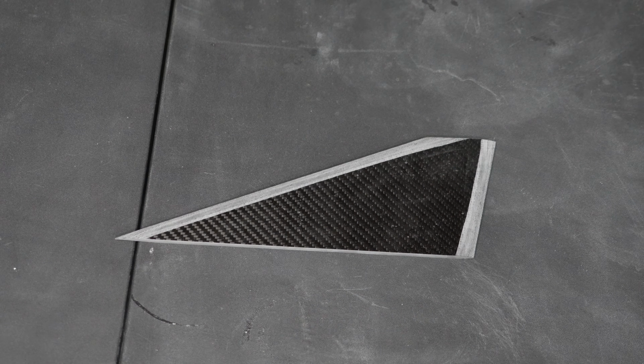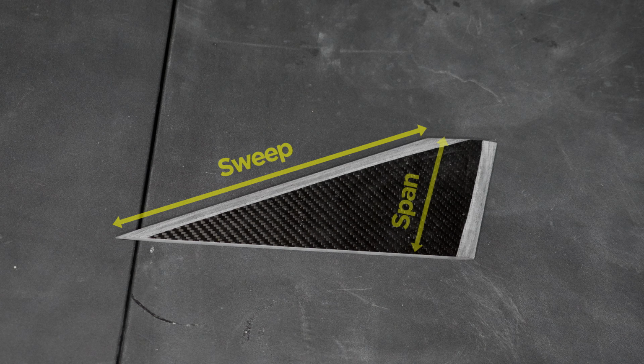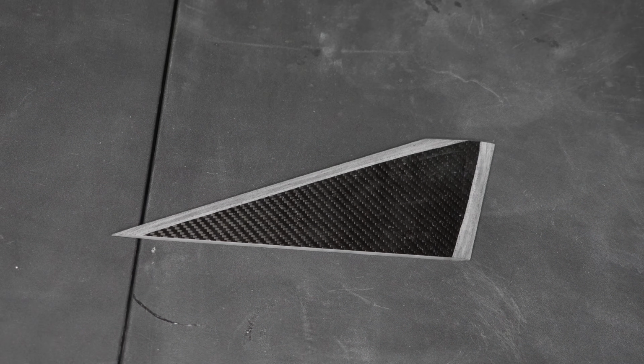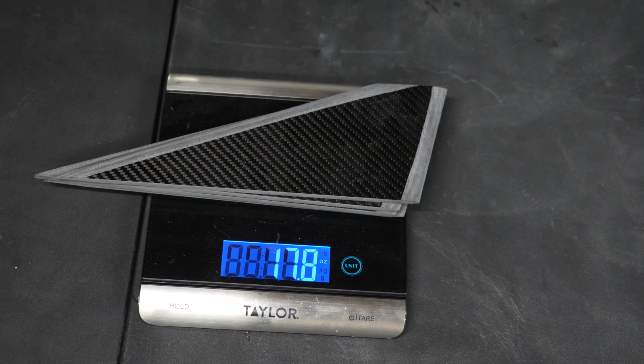Now we're on to the fins. You're going to want to measure the fin's root length, tip length, sweep length, and span. Once you've got those measurements, you're going to weigh the full set of fins at once, and then that's it. You're done with the fins.